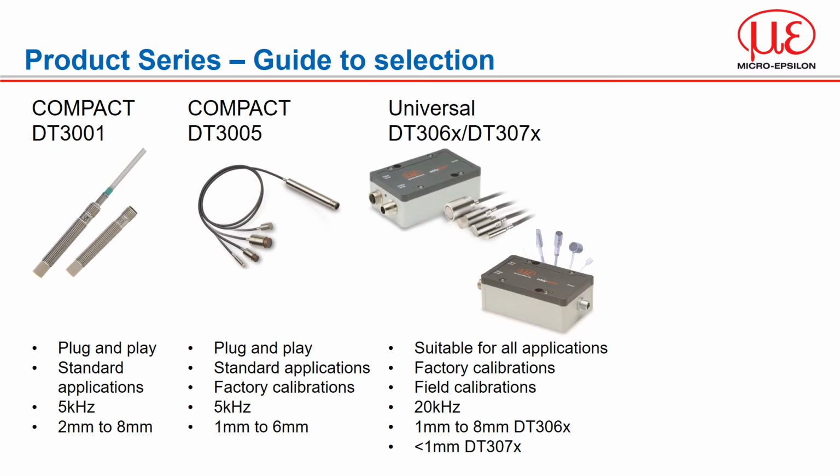The DT3060 and DT3070 series represent our latest controller technology, featuring Ethernet connections and the in-field linearization as you have seen earlier. Sensors are sealed for ingress front and back and are pressure proof. Check specifications for the individual sensors. Controllers can be calibrated for multiple characteristics so that you can have a sensor calibrated for both ferrous and non-ferrous materials. It features temperature output and limit switches for process control.